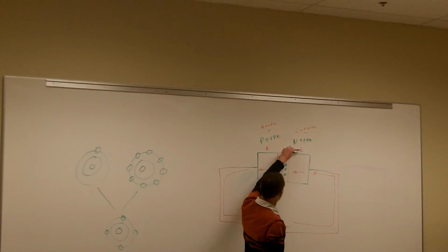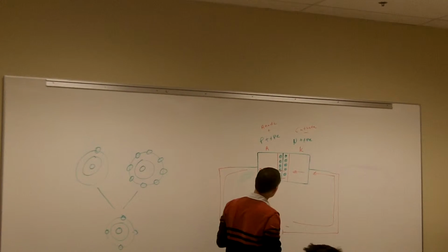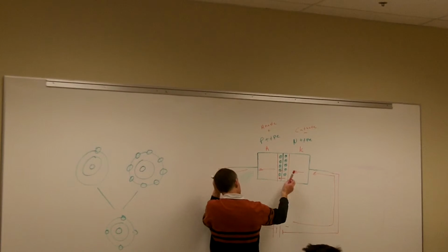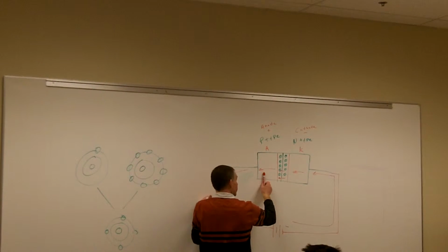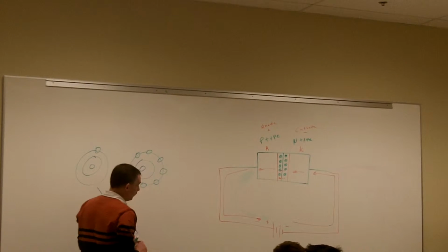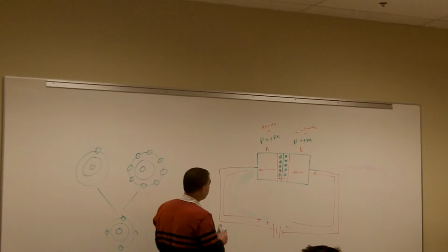And so if we see the K, that means that's our cathode side. That's going to be our more negative side of our diode. If I make this side more negative than this side of my P-type material, I'll get my current to flow through. So now if I switch my polarity around on it,